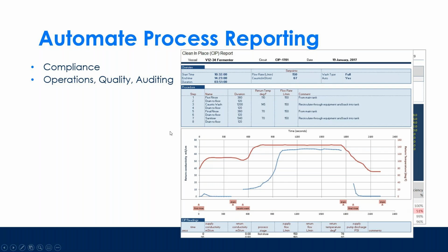There's the concept of safety and quality control with clean in place, which is common in beverage processes. Anytime there's liquid bearing vessels and pipe work that's holding or processing different products, these vessels have to be cleaned down and sanitized between production runs. And this is information that the government can audit. So these processes do need to be tracked and audited, and we need to ensure that they're being executed within the allowable guidelines.